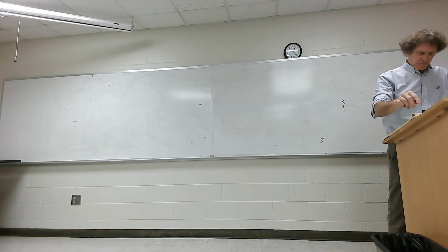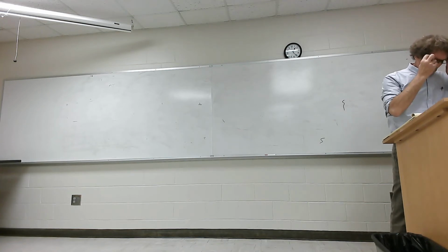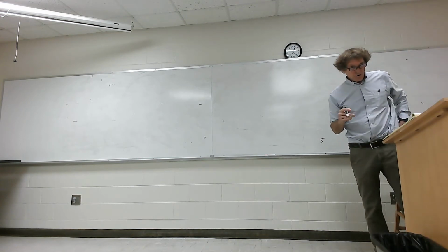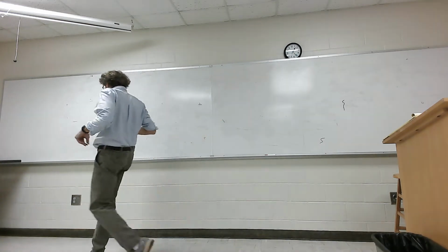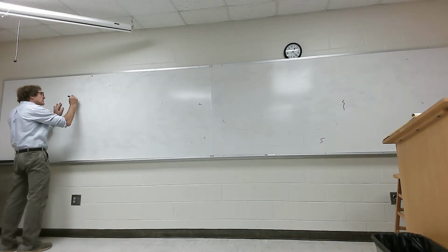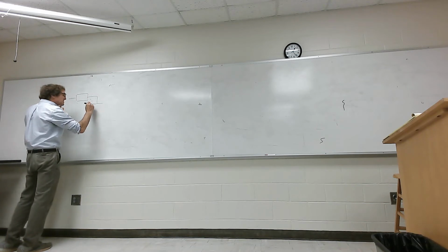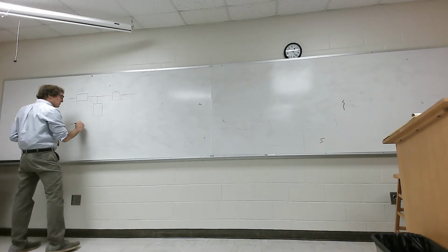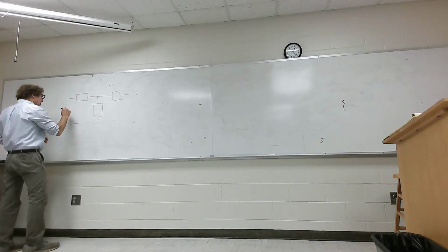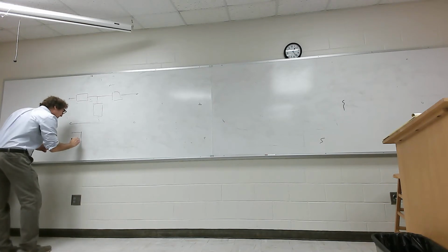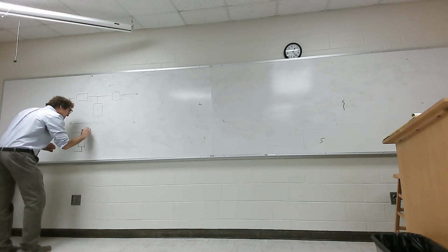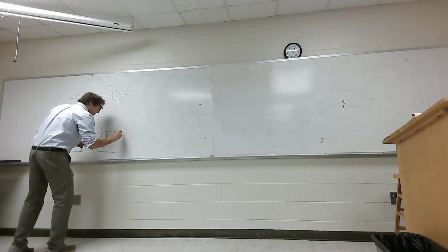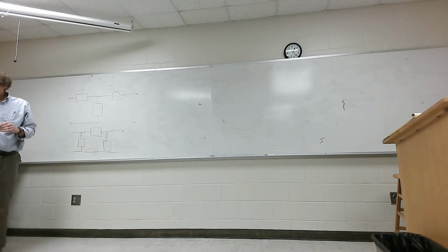So he shows you in his book, on page 590, how he goes about creating the band pass filter starting with a low pass. And again, there are 2 types. Remember, you can always have 2 configurations. You can have a T configuration, like such, with these just representing T elements. This is a T-type configuration for the filter, or you can have the pi configuration here. Are you with me? Let me try this approach.